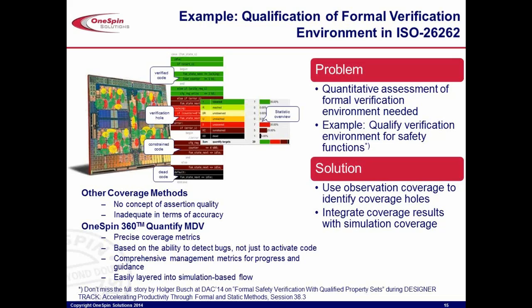So we have a tool called Quantify that computes the coverage of your assertion that is reported in a very intuitive way in an HTML report, which obviously has your summary metrics for management to see your progress, how much you've covered, how much you have not covered, but also a color annotated version of the RTL to see the part of code that you have covered, the part of code that you have not covered, which is very intuitive for the users.